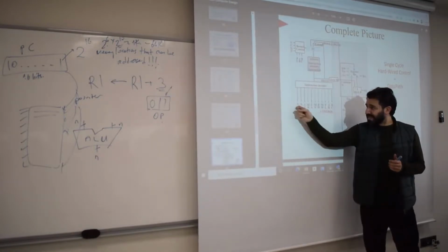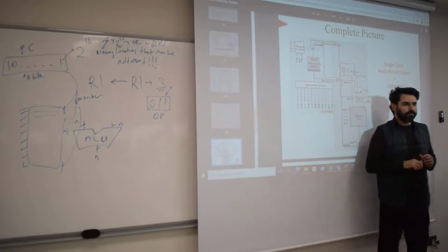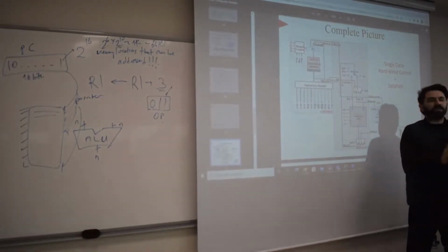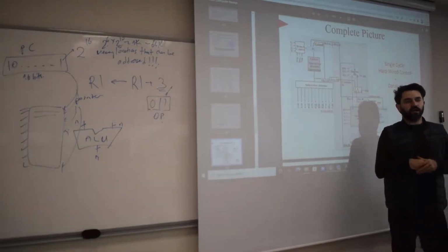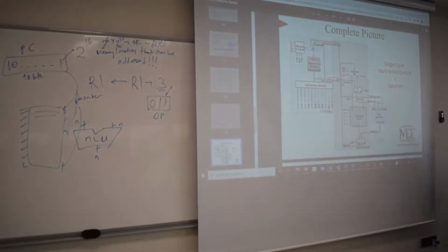So if you need DA, BA, AA in the next clock cycle, then put in a register, okay? That's the only difference, actually. It's not the only difference between single and multi-cycle, of course, but to the extent of the project, it will be just sufficient to know that, okay? The rest of them are just the same.